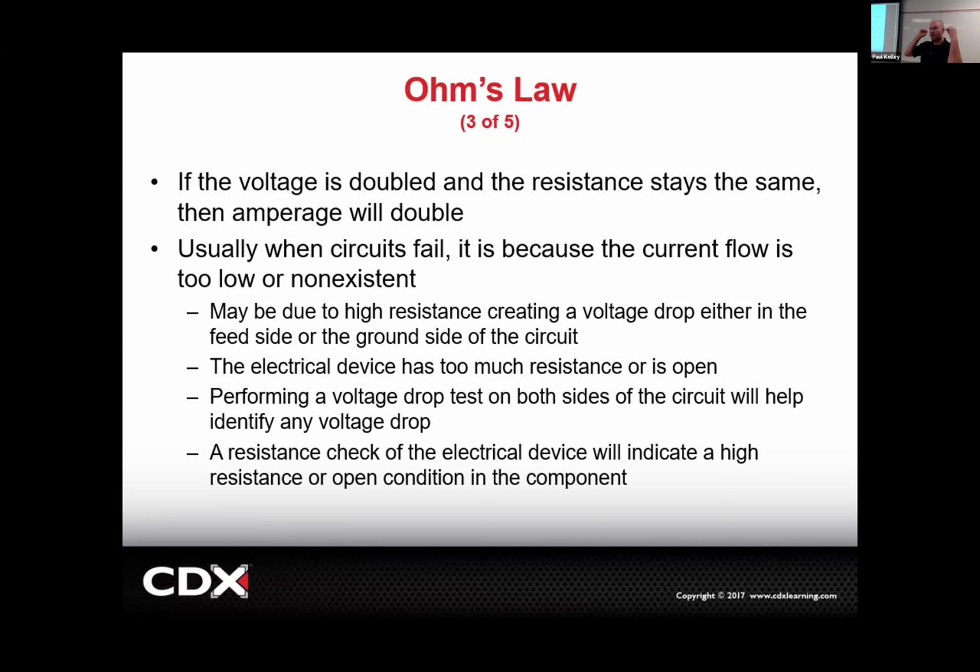Once you try to carry 9 amps, all of a sudden it gets to that point and there's only 3 strands and the electrons are crowded into 3 tiny little lanes, and it gets hot, and next thing you know, there's a lot of resistance there, and now your bulb is glowing dim, and so there is resistance in the circuit, but your resistance test passed it. Your voltage drop test would have nailed that, would have found it. You'd be like, oh, there it is. All right, so that's real world experience, just letting you know why this is better.